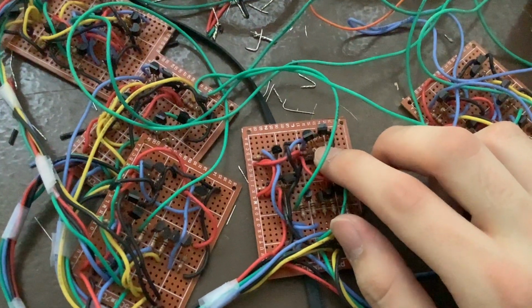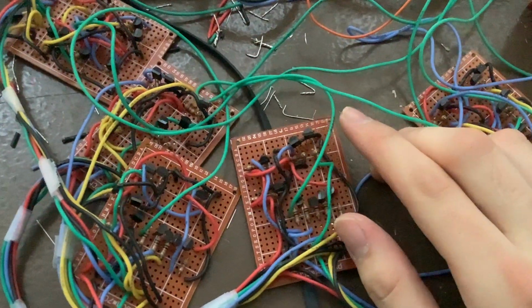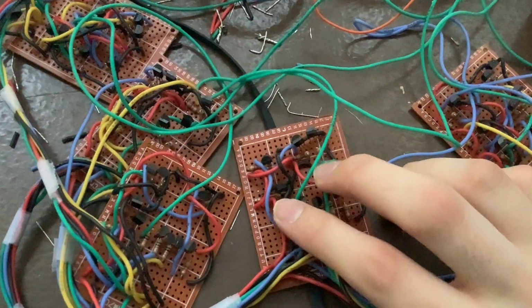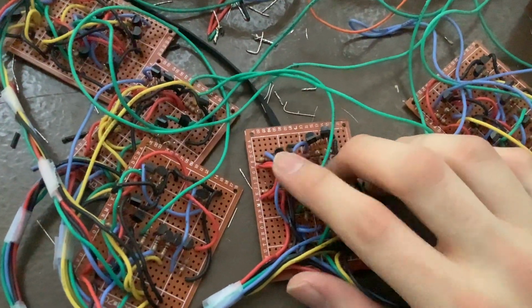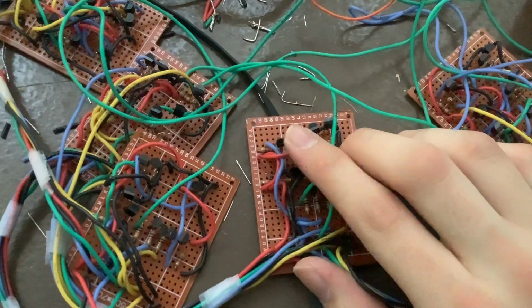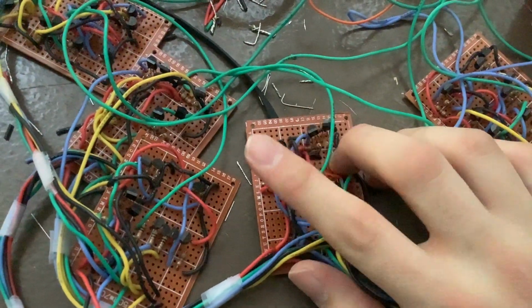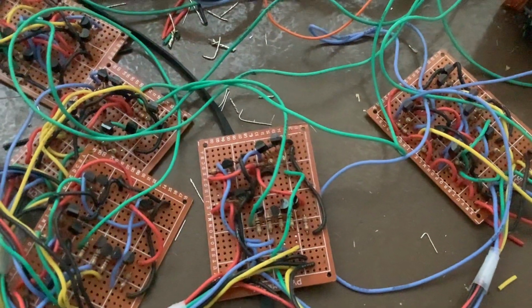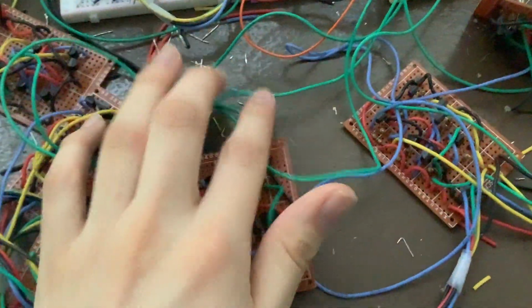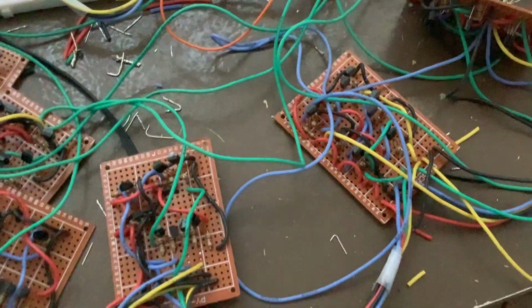only low if both of the inputs are high. And I just have a bunch of 2-input NAND gates. I also have inverters, which are just these single transistors. It's hard to see because of the wires, but these are single transistors, which work by inverting the input. So also, if I have an AND gate, which I have to implement, it's a NAND gate and an inverter. That just makes it simpler for how it works.